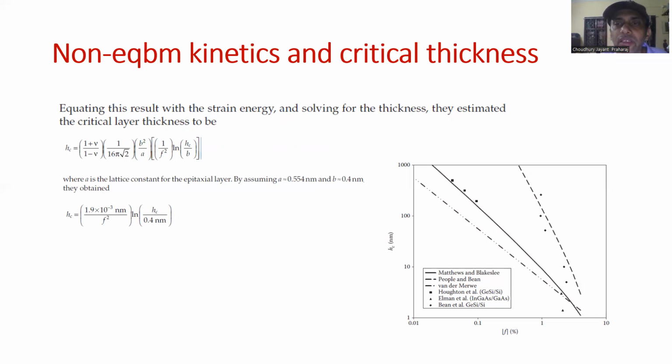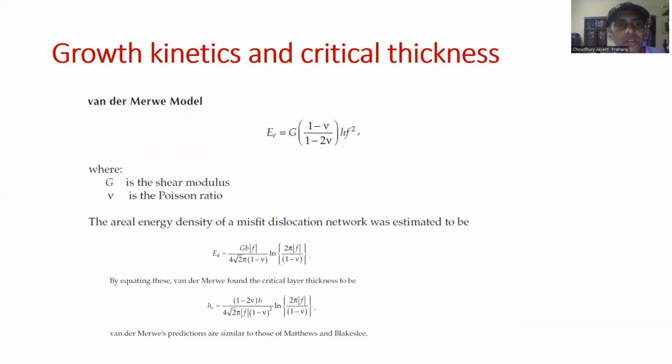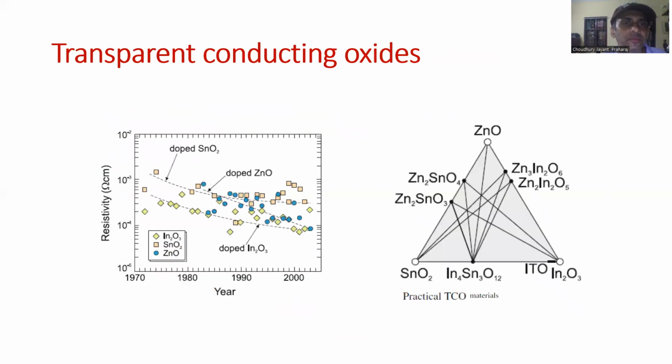designing the solar cells, for getting low dislocation densities, and for understanding and optimizing the piezoelectric polarization component of the polarization grading. So there is the spontaneous component, but the piezoelectric polarization component depends on the critical thickness and on the level of strain in these different epilayers and in these different graded layers. Growth kinetics affects critical thickness, and we can correlate theory with experiment.